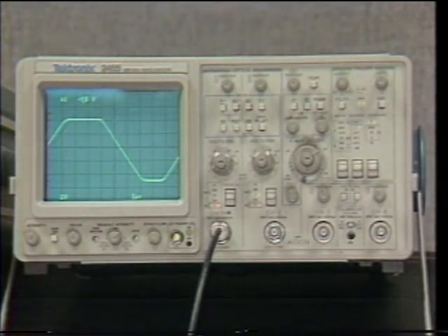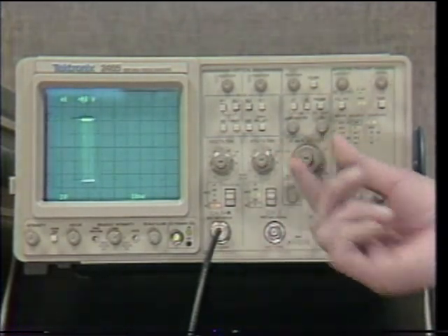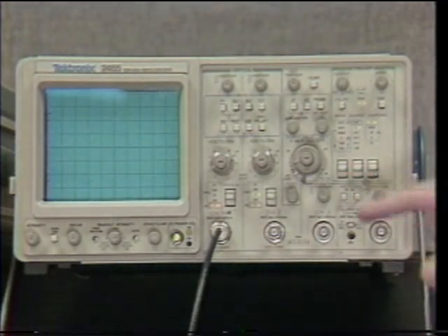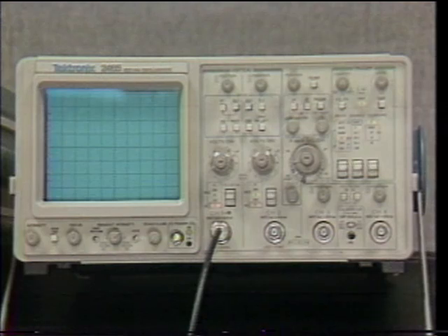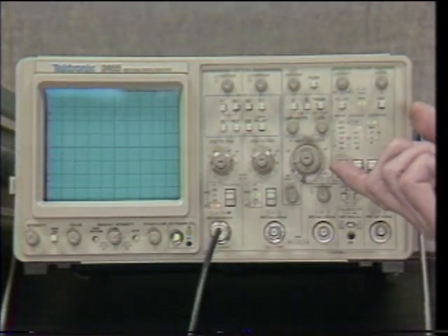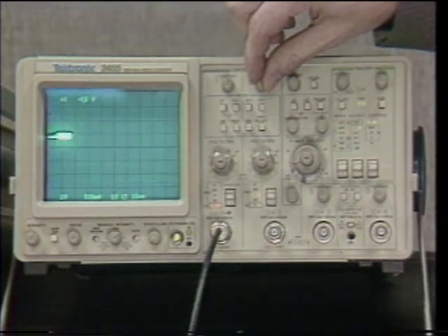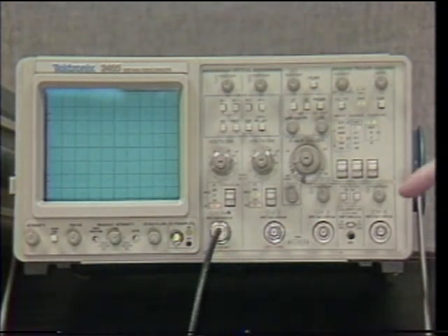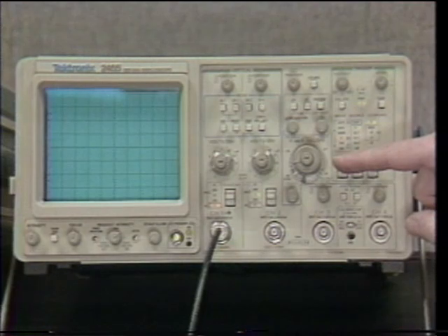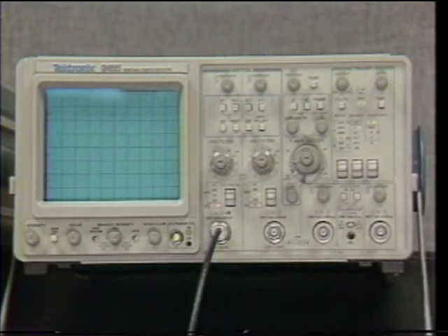To demonstrate the single sequence mode, let's first slow down the sweep so we can easily see what's happening. Now, selecting single sequence, we can see that we get one occurrence of the sweep and also one occurrence of the readout display after that. A single sequence is different from single sweep in that if we select more than one trace to be displayed, single sequence causes one occurrence of each of those selected traces and then the readout. As long as that sequence is not complete, the ready light is illuminated to indicate that, and the triggered light, of course, indicates each of the triggers as they occur.